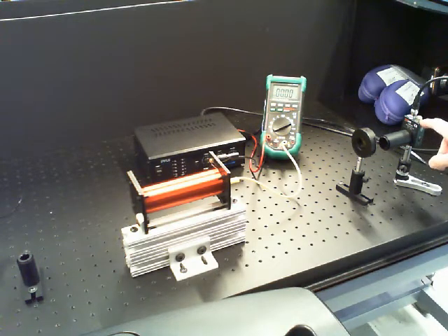Meaning you can disregard any signal on the detector which isn't at 45 hertz. So any sort of 60 hertz or 120 hertz noise from the lights, or whatever frequency these lights are flickering at, can just be rejected because it's not going to happen to be at the frequency that we set our function generator, or it's unlikely to happen to be at that frequency. The other factor is the phase of the signal.